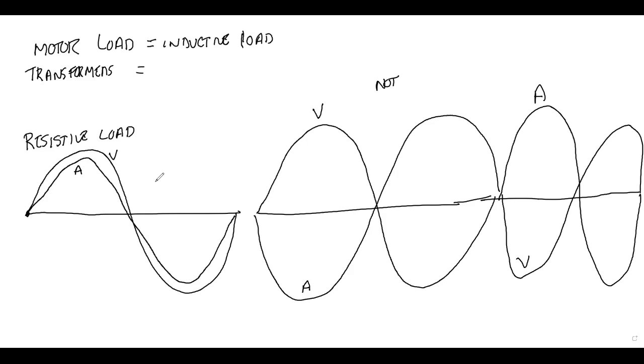We want to bring it as close as possible, which it never is exact, to in phase. Okay. So that was a little refresher that we had back from ELW 112. So we introduce capacitor banks on our system for those inductive nodes. Now, where geographically do I need to put them?